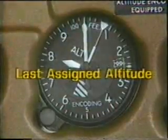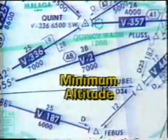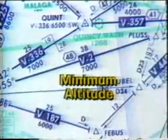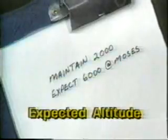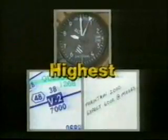The last assigned altitude. The minimum altitude, which is usually the minimum en route altitude or other charted minimum altitude. Or the altitude ATC has advised may be expected in a further clearance. Remember, you must fly at the highest of the three altitudes specified for each route segment being flown.